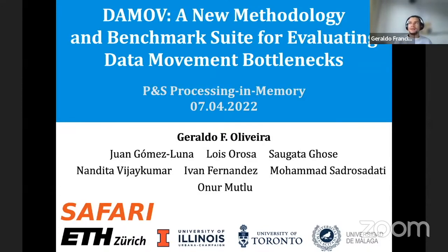And the simulator is targeting the x86 ISA, but there are tricks that you can employ to mimic the same type of ISA that these HBM-PIM architectures are going to be executing, because in the end it's just memory activations and memory precharges that are being translated into instructions issued to the PIM accelerator itself, which is already heavily supported by our simulator.